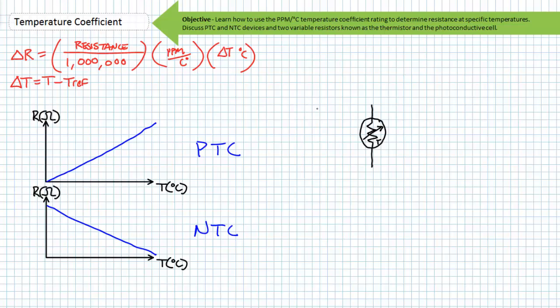I like this one because the arrow modifier is used extensively in hydraulic schematics to mean it is a variable device. A thermistor isn't variable in that there's a thumb wheel or a valve handle you can use to change resistance, but rather via temperature, the resistance varies radically up or down. When I say radically, I mean more so than an ordinary resistor, because as we've learned, all resistors change resistance at different temperatures. This radical change can be used to your advantage.